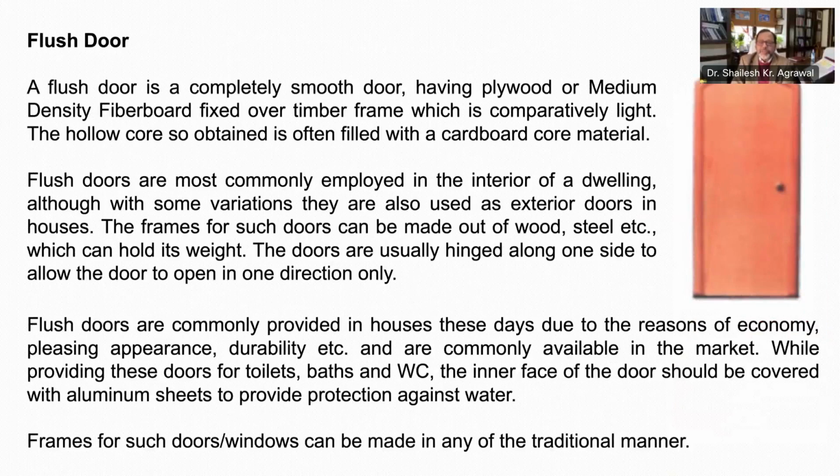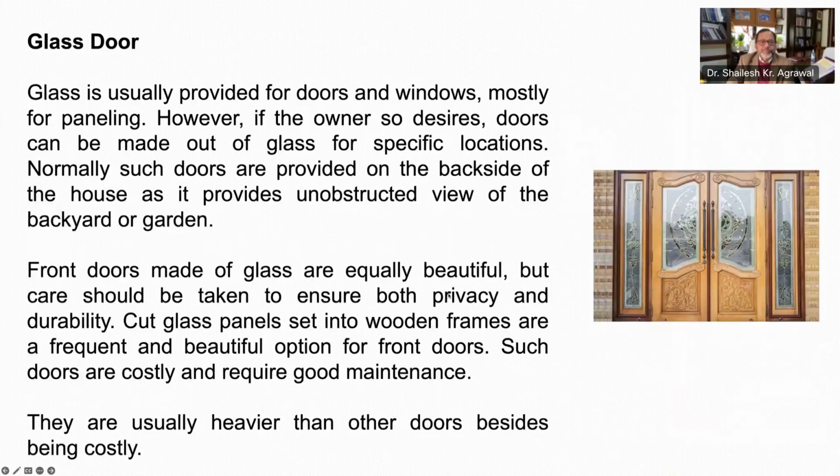The frames for such doors can be of either wood or steel. The doors can be hinged along one side so as to allow opening in one direction only. Remember, while using these doors in wet areas, the inner face of the door should be covered with aluminum sheet to provide protection against water.